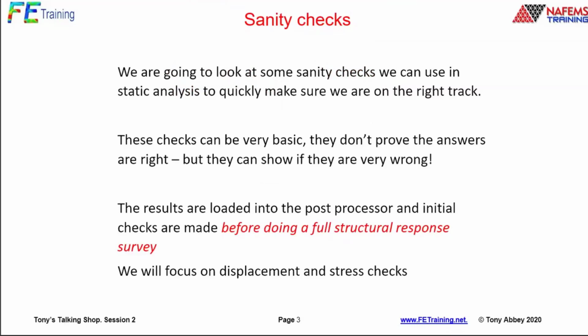I'm focusing here on linear static analysis, just to make sure we're on the right track. The idea is that these checks are very basic. They don't prove the answers are right, but they hopefully will show if they're very wrong, if we've got the wrong idea, or something fundamentally flawed with the model. Now the results are going to be loaded in the post-processor after we run this analysis. What I'm looking for then is initial sanity checks that should take no more than 5-10 minutes. Is everything in good shape?